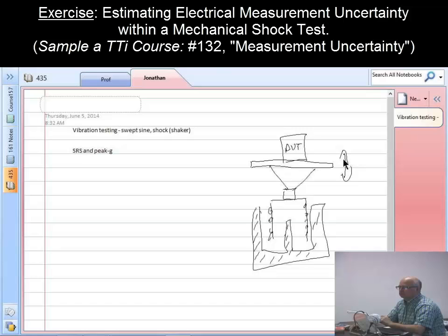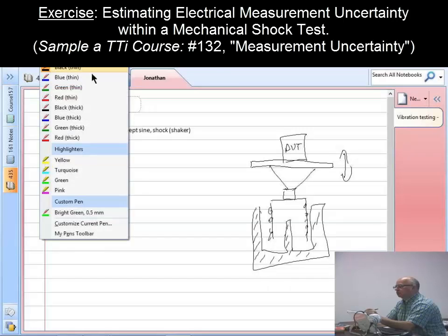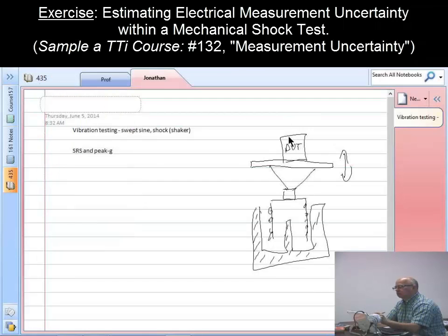And then we'll have a couple of different accelerometers, but for this case we'll just have one accelerometer on the fixture. Do you normally mount it on the head expander? Where do you normally mount your accelerometer? On top of the UUT or right next to it? It kind of varies. Usually we'll typically mount it as close to the mounting points, but depending on the package, if there's any space constraints, size constraints, or interference issues, it'll vary. So in this case, we're just going to have one accelerometer, to keep it a simplified version.